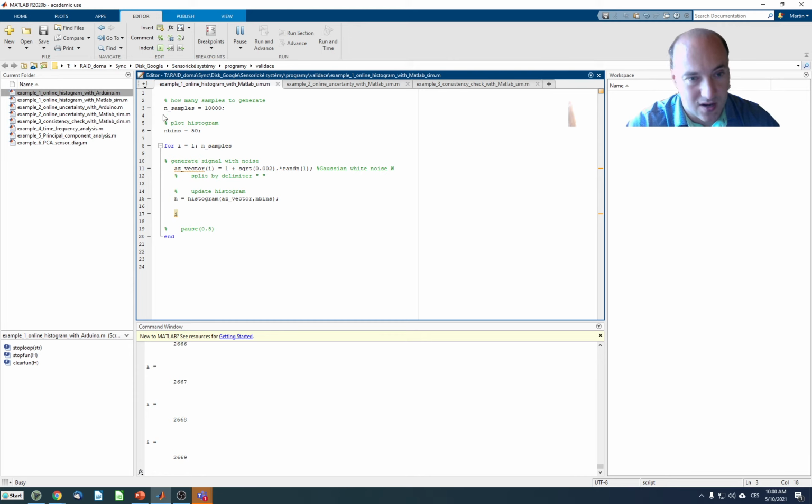So you can run this algorithm in real time. You can simply get the data from some sensor. You don't need to plot the histogram, although it's sometimes quite useful to plot it, for example, on the screen of some measurement instrument. And at the end you can just calculate the variance. And if your variance has changed suddenly from some previous value, for which you know that the process works within those boundaries, then you may raise an alarm and say, attention, something has changed in the process, and there might be something wrong.